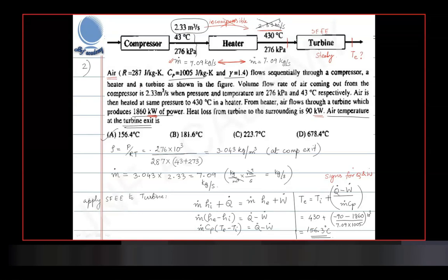For a jet engine, you want kinetic energy. So the main device is you want to expand the hot gases in a nozzle. The turbine is sitting only to drive a compressor for a jet engine. But in a land-based gas turbine engine, the compressor work will only be a small part. Majority of the turbine work will go for running the generator. So depending on the situation given, you should be able to make the decision. Does that clarify? Okay, great.